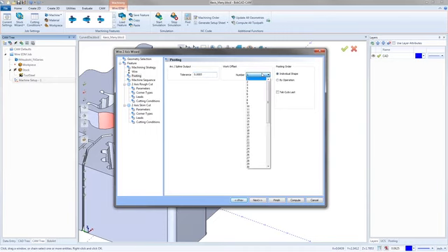Right here's work offset. So you have by default, what's this one give me? 59 different work offsets. I'm going to keep it on number 1. And that'd just be your work offset, G54, G55, 56, and so on. And then right here is your posting order. So there's 2 ways to post in BobCAD.